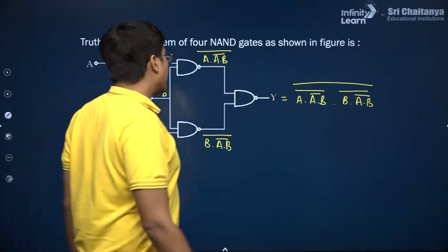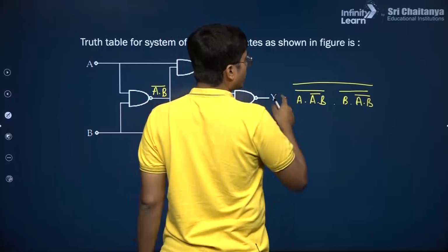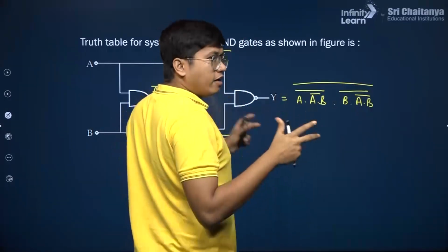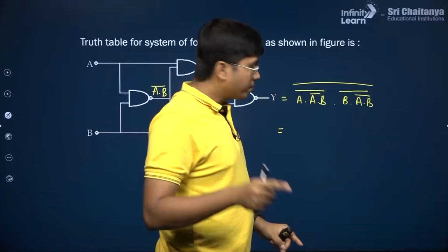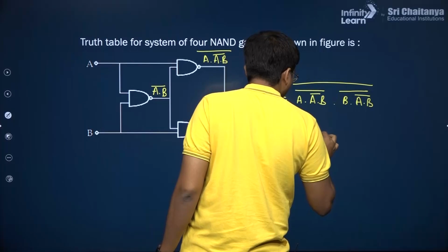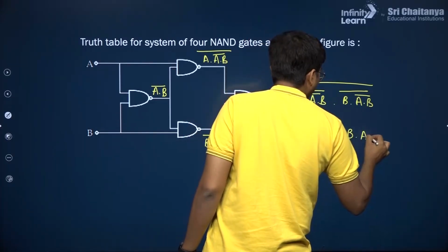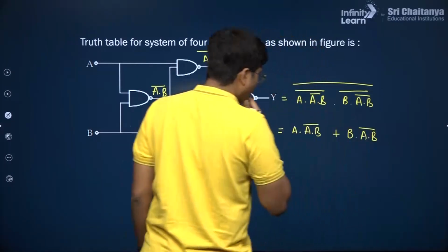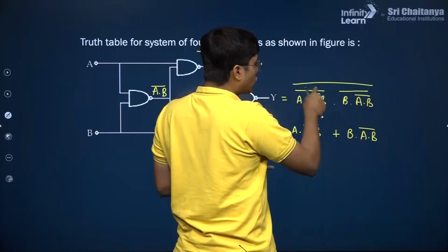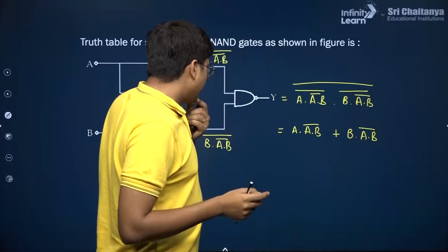So let's simplify again. De Morgan's theorems will really help us out here, because by De Morgan's, if you have the bar over 2 multiplications, it's split up as individual pieces with the OR sign. So you'll effectively have A dot B bar plus B dot A dot B bar. Why? Because these two would separate in an OR function with a not on each. So not of not will cancel out the nots, make it positive. Next, what can we do?